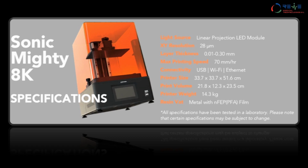In SLA technology, the biggest advantage is that you're printing layer wise. So if you print multiple objects simultaneously, although it will use more material, the time will remain the same. Overall, if you print 10 objects together which are in the same line, it will print all 10 objects in the same time. The only thing that differentiates the time is the height. So the taller the item is, the more time it takes to cure and produce. So in mass production, if you look at producing more parts, this is the technique to go for. Even SLA and SLS both are the go-to methods for mass producing parts.